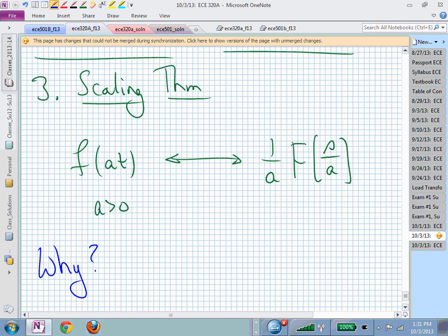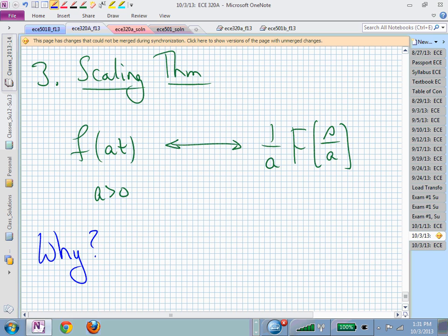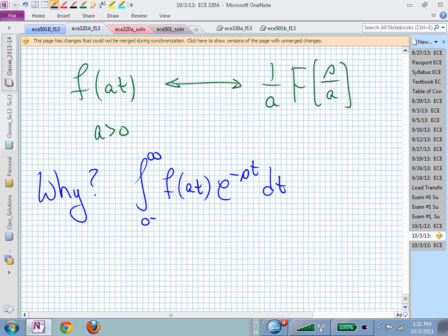Now you can show this from the definition of the Laplace transform. You can simply substitute the waveform, the signal that you're trying to compute its Laplace transform for, into that location in the integral, scaled by e to the minus st dt.